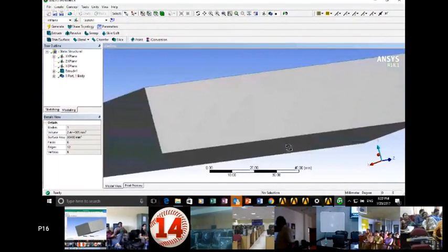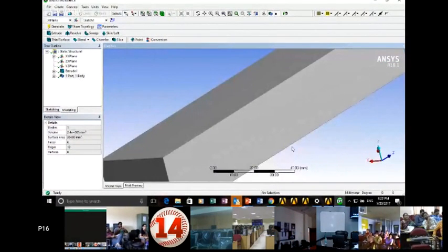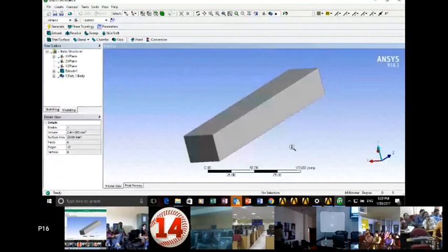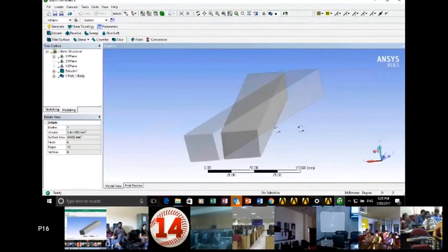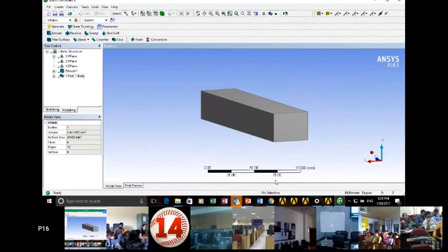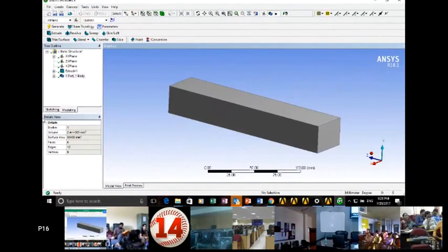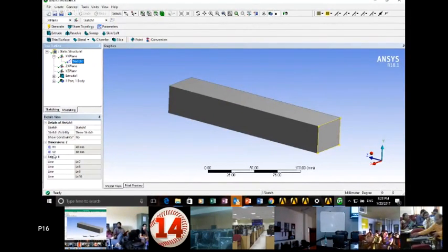Over here, we'll take the example of the same beam which we had earlier taken for our what-if study. The difference between the previous example and this example is that we are actually going to optimize this beam considering the factor of safety. Got it? As I told you earlier, we have parameterized the cross-section dimensions.